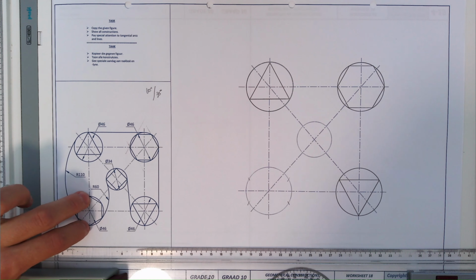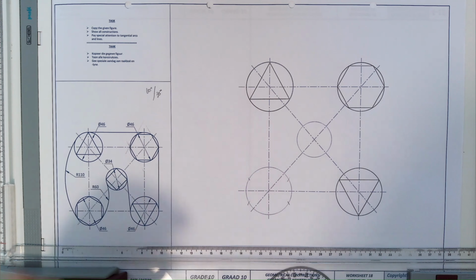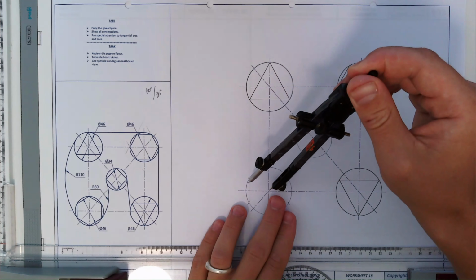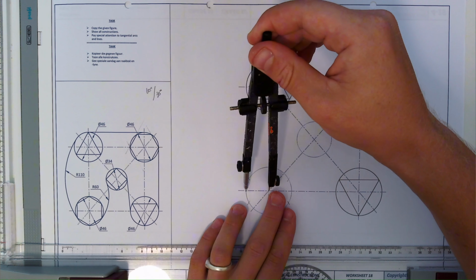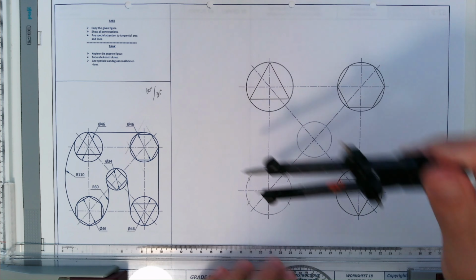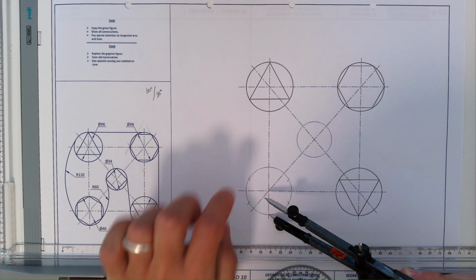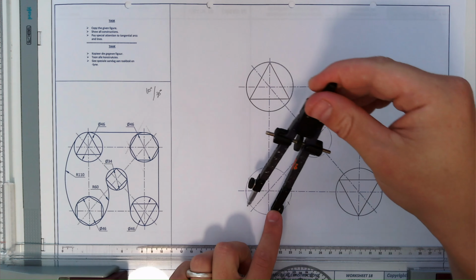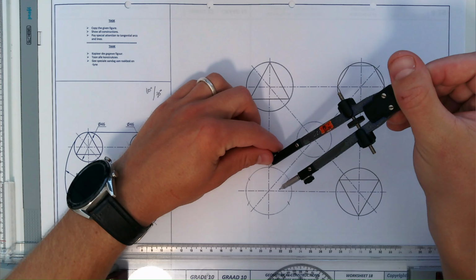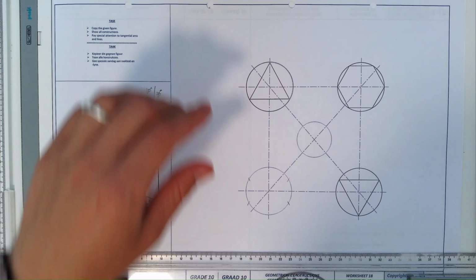Because the points are touching the circle there and there, where the middle point connects to the circle on those two points, you take your compass, you get the radius, which is half of this diameter. You're going to put your sharp point where the points will be, which is there, and you take this radius and you mark it off on the circle on the left and on the right, and on the left and on the right.